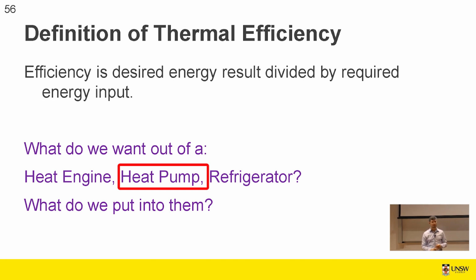Gas is somewhat similar. You burn a gas, and it makes it hot. My heater over in WA is a heat pump heater, and what that is, it's like a refrigerator bolted to the outside of my water tank, right? It draws in atmospheric air, it makes the atmospheric air colder and spits it back out. So when you feel it, it feels cold, and the heat that it extracts from the air is what it puts into the water, as well as the electrical power that it consumes goes into the water. And so it can be 2 or 3 times more efficient than a standard resistance-based water heater.